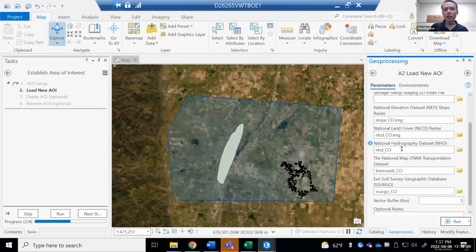The next thing is trying to identify areas or bodies of water, and this includes lakes, rivers, what have you, that you certainly don't want to stage your waste in, right? You want to avoid that. We also take into consideration that you may want to have some distance between you and that water source, in case you're working with some type of contaminated waste, such as bio or rad. You definitely don't want any of that leaching into any of your local groundwater or water sources.